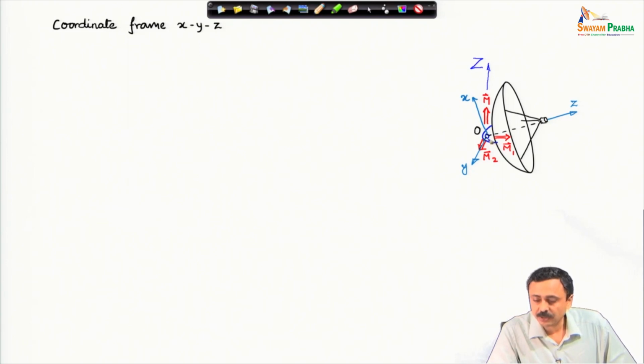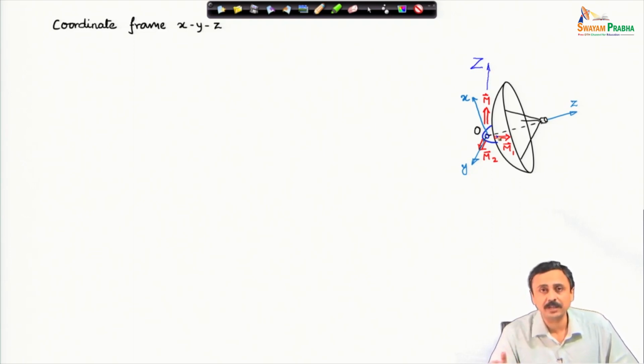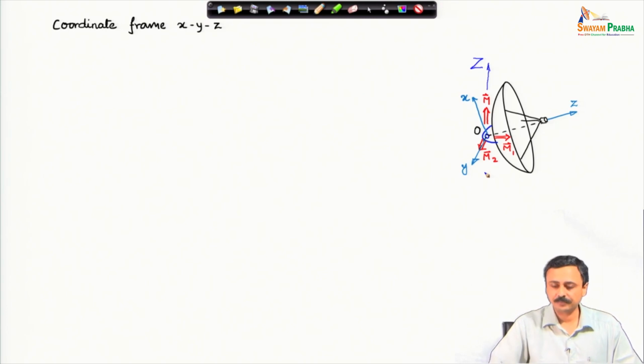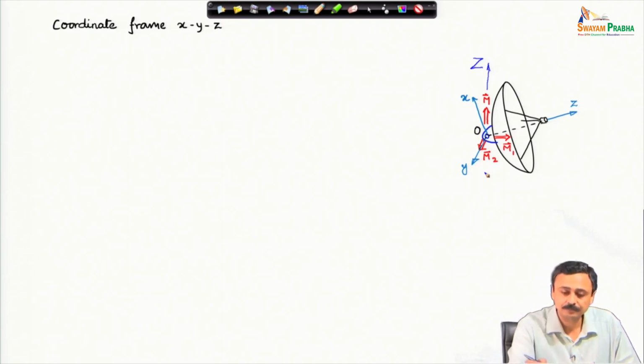In addition to that, because the antenna cannot rotate about the other directions, there must be moments in general. Let us see, because to start with I do not know what are the various moments. Now, I have taken a general situation where this capital M is the applied moment, and m1 and m2 are moments which are unknown to me. My equations will tell me what exists or what are their expressions.